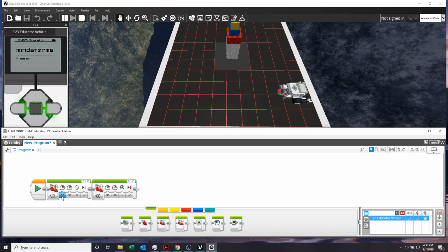The motors are not installed backwards, so be careful of that. This is not a constant. In this situation, on this particular robot, positive 50 and positive 50 means the robot is moving forward at 50% power. So if we move forward at a positive 50, we now want to move backwards. So we'll put a negative 50.